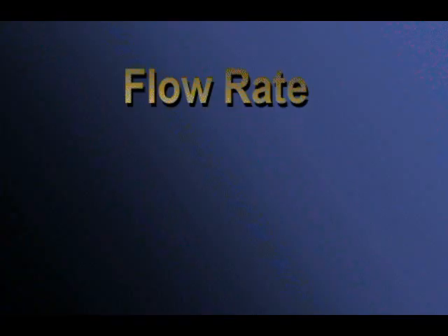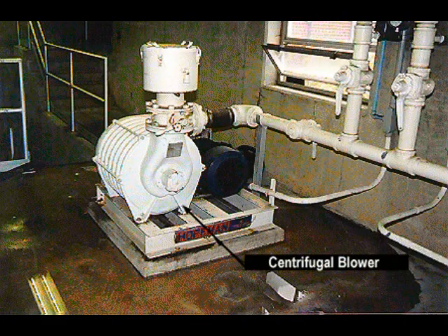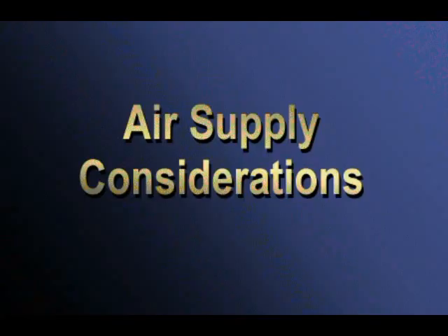The rate of flow is controlled by how much air is forced through the injector. The rate of flow also depends on the depth of the air injector below water level. The deeper the injector, the more liquid will be pumped. Since airlift pumps need an air supply, they are often used in activated sludge plants to pump side streams. The same blower that supplies air to the aeration tank provides the air for the airlift pumps. While this dual usage of the blower is convenient, there can be problems.